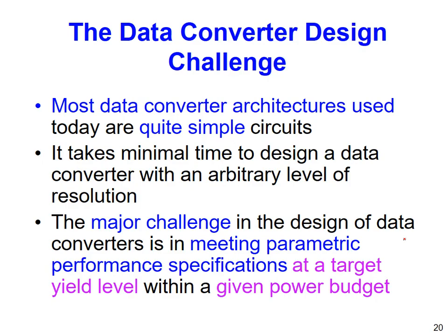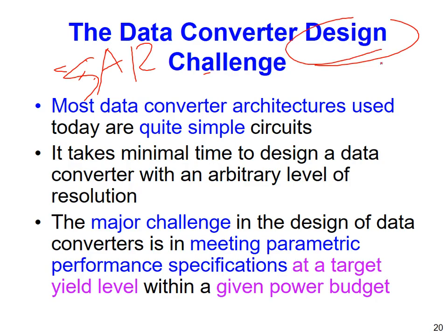Even though there are quite many architectures, most of the ones we use are quite simple. I think nowadays there are two major structures: SAR first of all, and then pipeline. That's it. Forget all the others. We still have flash ADC, but it is only used for very high frequency. So for on-chip applications, usually SAR first. If SAR cannot fit your need, then maybe pipeline.